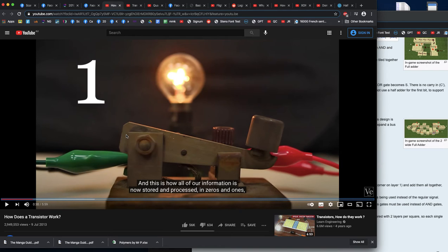Yeah, so for example, we could turn A on and leave it on for about 10 minutes, and then switch A off, and then turn C on. It's easy to identify which one C corresponds to because it's going to be the one with light coming out of it. But if we wanted to differentiate between A and B, we could feel the temperature of an incandescent globe. Now, this wouldn't really apply for LEDs because they don't heat up the same way that incandescent globes do, because they were inefficient. So I just thought that was an interesting thing.